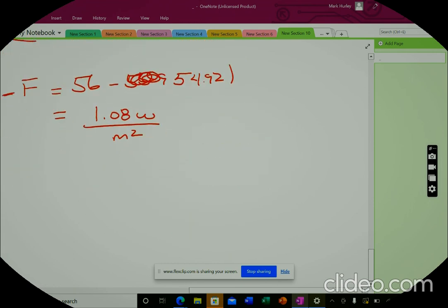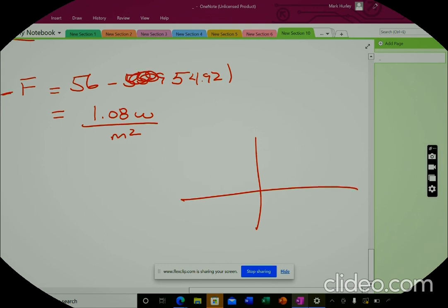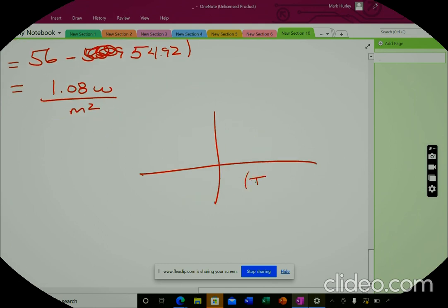And the reason for that, when we did our tests, we look at the equation. Here we have the heating load as the x variable, and the y variable is the heat flux prediction. We get a line, it's linear, with the slope equal to tau. If you increase the heating load by 1, the flux increases by the slope, tau. And what we found is the actual values were pretty close to the line, and the R squared value was 0.957, which is very close to 1.